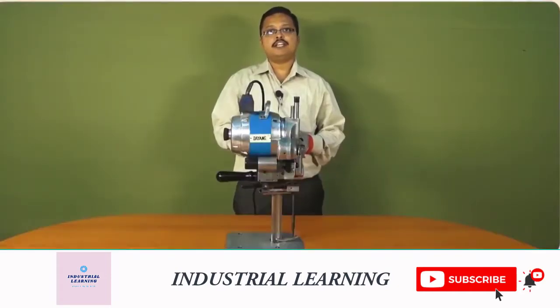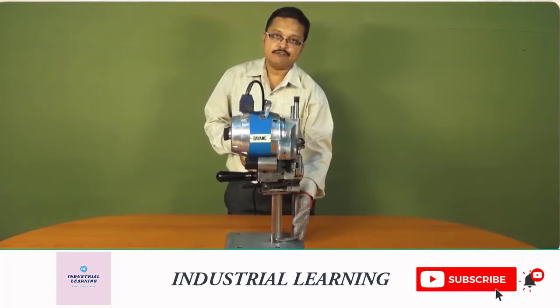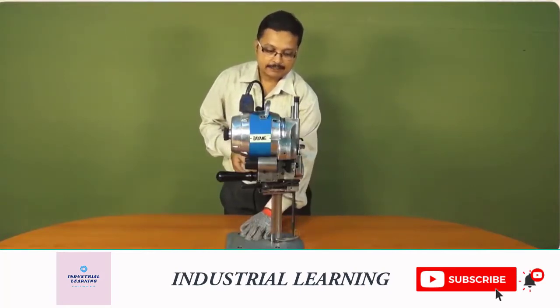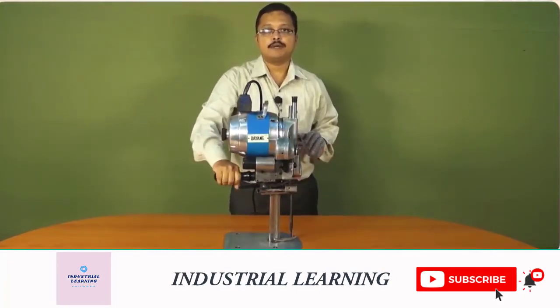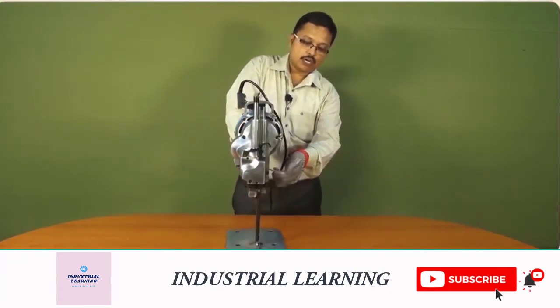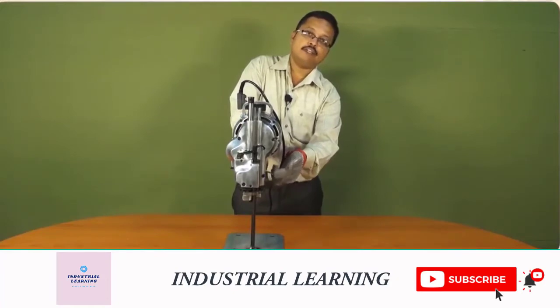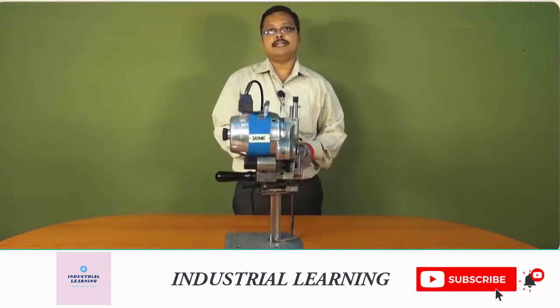This is a straight knife cutting machine. This machine is used to cut in bulk fabric lay in an apparel manufacturing unit. Essentially, this machine consists of a straight knife, a knife guard, a base plate, a sharpening mechanism, a motor and a handle for the operator to operate it. The entire machine is switched on and off with the flick of this switch. Now we will see each part in detail.